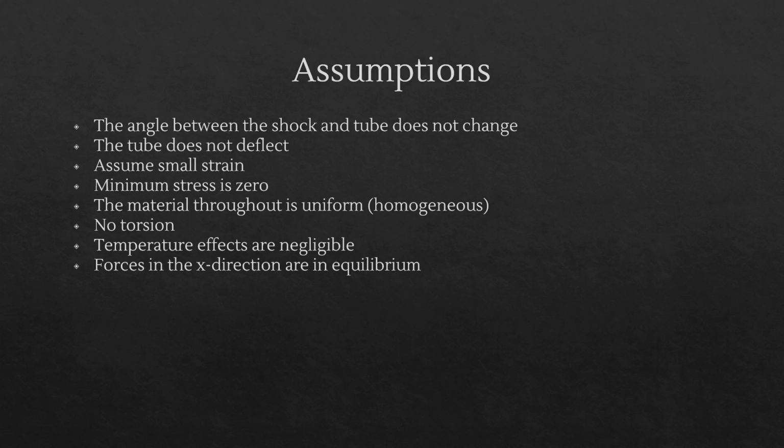Assumptions. The assumptions we use throughout the project are: the angle between the shock and the tube does not change, the tube does not deflect, we assume small strain, minimum stress is 0, the material throughout is uniform or homogeneous, there's no torsion, temperature effects are negligible, and forces in the x direction are in equilibrium.